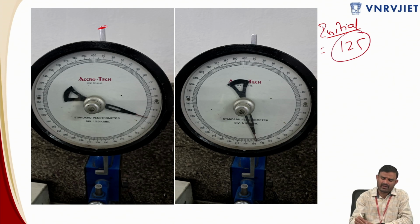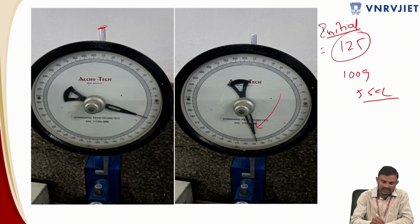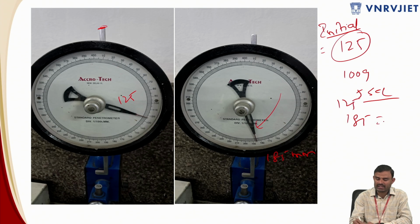After the application of 100 grams of load for 5 seconds, the depth of penetration has increased, and the needle goes inside. Again, if I move the graduated rod inside, it will show a different reading compared to the previous condition. Earlier it was 125, and now it is around 185 mm. So 185 is the final reading and 125 the initial one. The difference of readings is 60, so 60 is the penetration value.